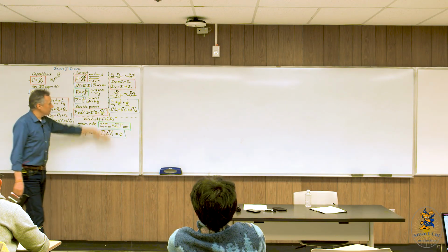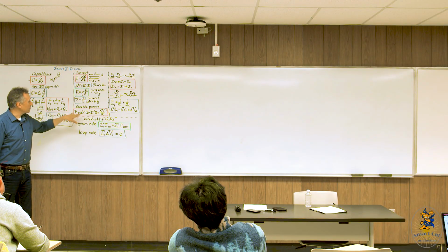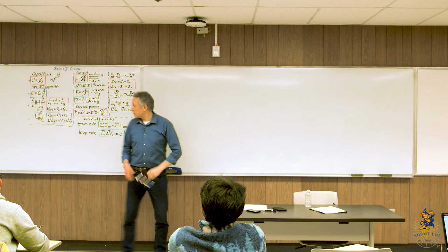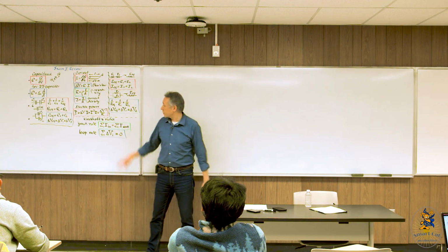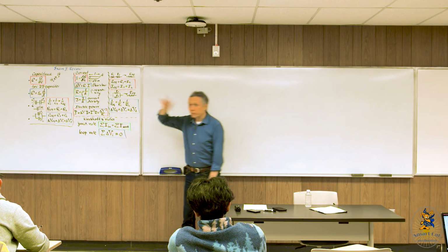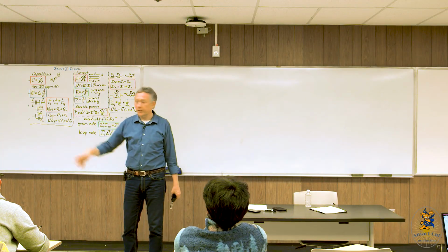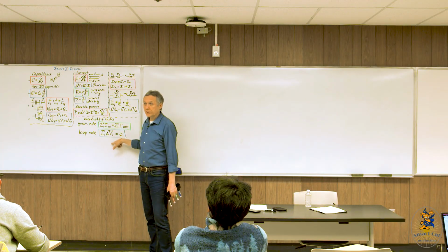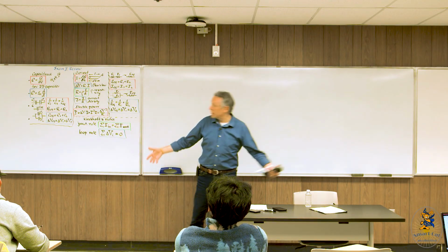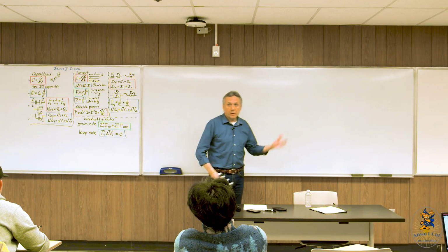And then the final piece of material which we discussed, electric power, of course, and Kirchhoff rules, the junction rule: the total amount of current entering the junction point must be equal to the total amount of current exiting. In the loop rule, if you take any loop in the circuit, walk around in a certain direction, adding all the potential differences across each element, when you get back to the starting point, you must get 0. Right? Okay, so essentially that's what we need.